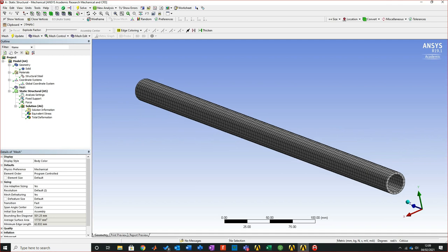There's a few things you could do. I mean, the most common one is people saying, right, well, let's just make the mesh super fine. You could do that, easily do that. So if you look here where I've got sizing and I've got default resolution, I can put a bigger resolution onto it. Where I've got spanning angle,